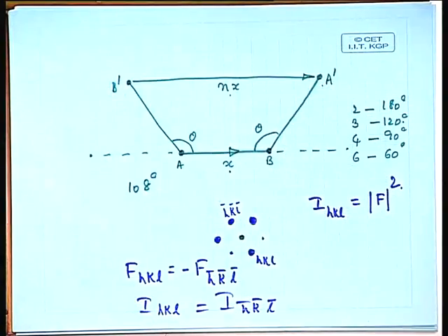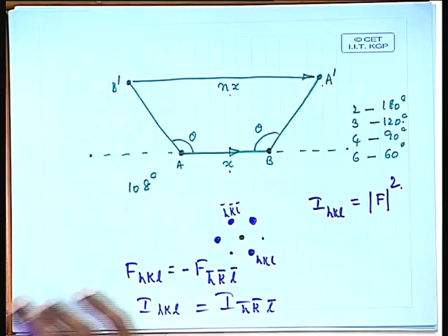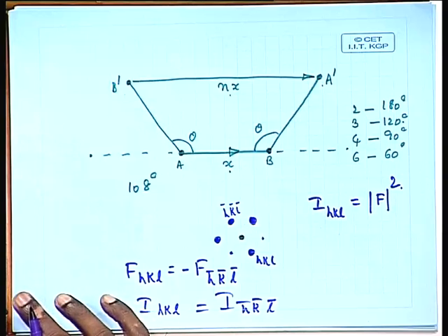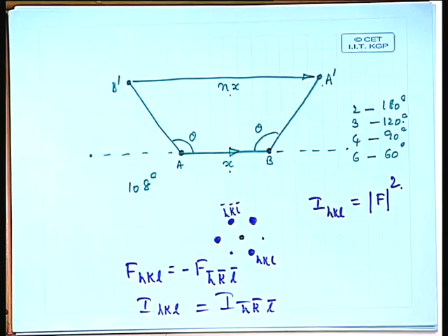So if you look at a cubic crystal in TEM or a pinhole X-ray diffraction, they are basically similar, in that you get diffraction spots instead of diffraction peaks. If you put a crystal inside a TEM and pass the electron beam, you get this kind of a 6-fold diffraction pattern. Immediately one thing is clear from this: the crystal that you are looking at is one of 3 possible crystal structures. What are the 3 possible crystal structures which can give you this kind of a diffraction pattern?